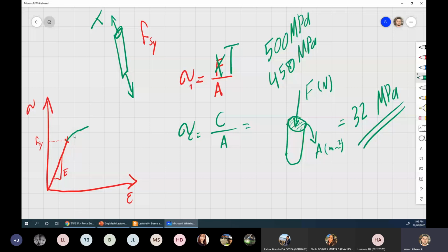At this point here, you can see that with minimum force, or minimum stress, we get too much deformation. Look, my line, instead of going up, is going more to the side. That means I apply a small amount of force and I get too much deformation. That's where we start getting the plastic form. And at this point, there are many different scenarios that may happen.